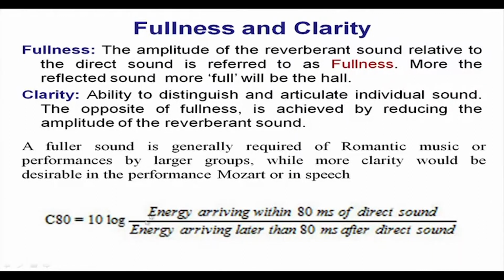But if the reverberant sound is also very intense, then what will happen? The fullness is very high, but the clarity will be confused, because all reflections will come together to me. So, clarity is the opposite of fullness of the sound. Okay. So, clarity C80 is defined by the energy arriving within 80 millisecond of the direct sound and the energy arriving later.